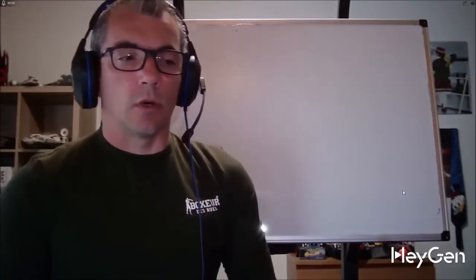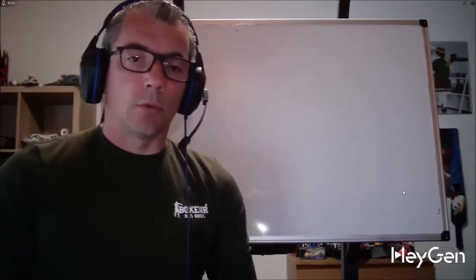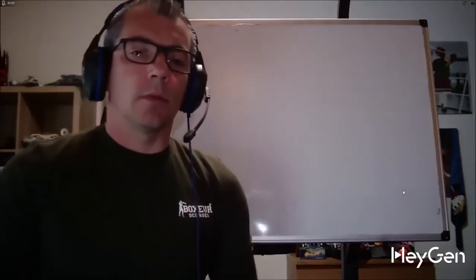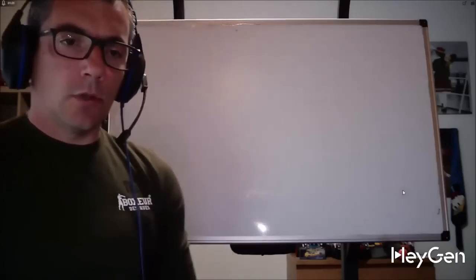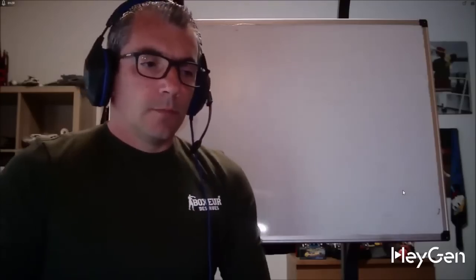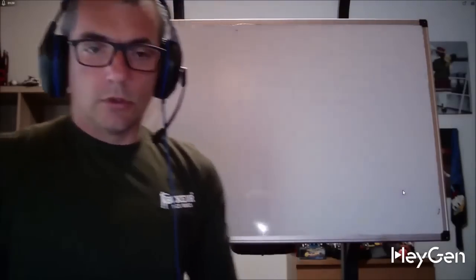Previously we explored clearing a part with point-to-point programming. Now, on the whiteboard, I want to explain a macro's concept. Consider a piece like this. We're not focusing on dimensions now, but after facing it, we have material left to clear. Today we're talking about the roughing macro. I call it a macro, but in the manuals they refer to it as fixed cycles. So I apologize for not making that distinction.